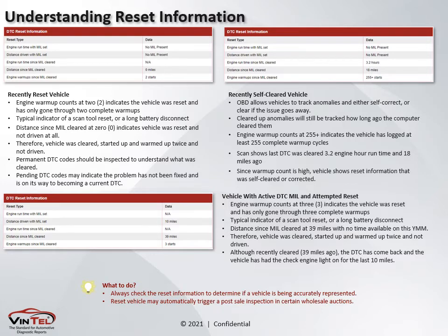But at this point, what needs to be understood is that permanent DTCs, those are DTCs that have been marked and cleared or have been around, cannot be cleared by a scan tool. They can only be cleared by self-clearing after between 50 and 100 warm-ups. The reason being is that technicians can use this to repair the vehicle. But from our standpoint, we can look to see if someone is trying to mask something by clearing the car. These are things that they're trying to mask. Understand that.